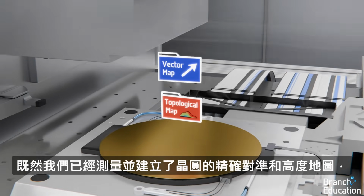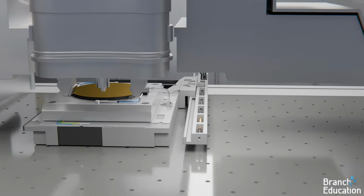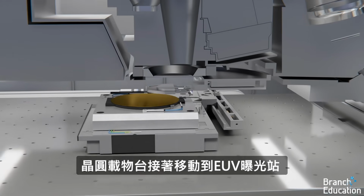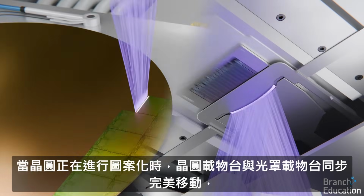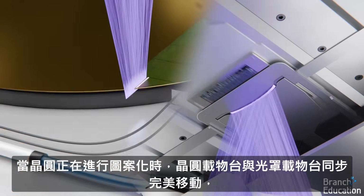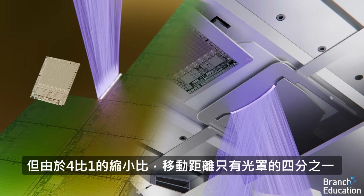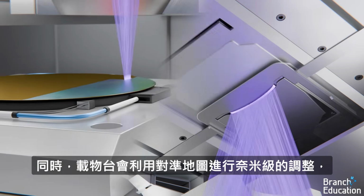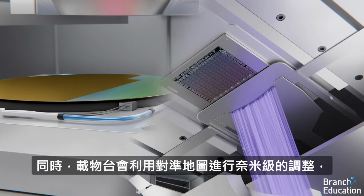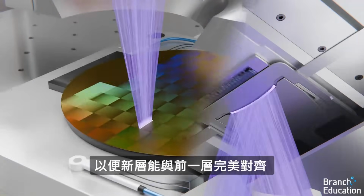Now that we've measured and built the exact alignment and height map for the wafer, the stage next moves to the EUV exposure station. As the wafer is being patterned, the wafer stage moves in perfect synchrony with the reticle stage, but only a quarter of the distance due to the 4:1 reduction. At the same time, the stage makes nanoscale adjustments using the alignment map so that the new layer perfectly aligns